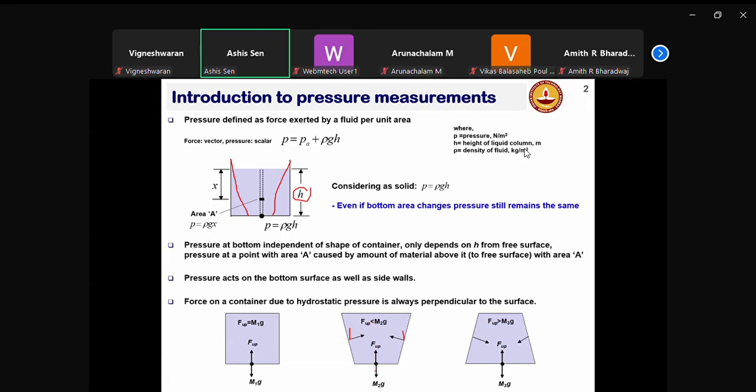This force balance is coming from the side walls. Similarly, if you have outward slanted side walls, the reaction force will have a component in the downward direction. So in this case, this F up will be equal to m g plus the reaction force in the side wall. That is how, if you change the shape of the container, although the force balance of the bulk fluid element is ensured, the pressure at the bottom will only be a function of the height of the liquid column.